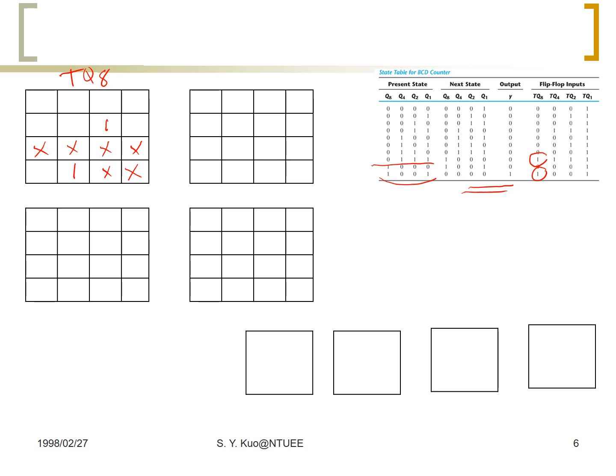Same thing, we go here to TQ4, it will be 1 at the 3 and the 7. So that is the 3 here, we put 1, and that's the 7, we put 1. Again, we put don't cares in the same 6 positions, and then we move on to TQ2, which is 1 at 1, 3, 5, 7. So we write here 1, 3, 5, and 7, and we have don't cares in the remaining 6 positions, and TQ1 will be 1 in all 10 different positions. So these are ones, and these are don't cares. So this is the simplest.